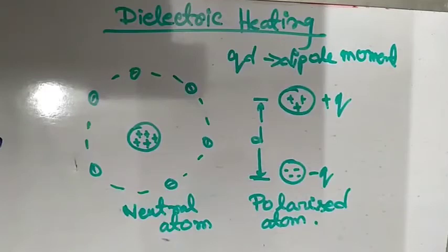However, if the electric field applied is very strong, it may overstress the charges and hence some electrons may be knocked off from the outermost orbit, resulting in rupture of the dielectric medium. Also, as far as possible, no air gap should be left between the electrode and the specimen to be heated, as normally the dielectric strength of air is smaller than those of dielectric materials to be heated. Also, for any voltage applied across electrodes, the electric field intensity in the air gap is higher than in the specimen. Now, if an air gap is left, the air will be ionized and may result in breakdown.